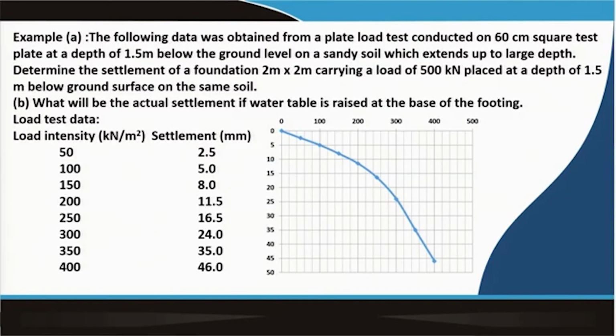by using the lab test data, because as I mentioned, field test data for clay soil we have to use with caution, because the field tests are short term tests, but the behavior of foundations on clay soil is long term. For example, the plate load test data. That plate load test is short term, but as you know, the consolidation takes a huge time for clay soil. So, those field test data like the plate load test in case of clay soil, you have to use with caution. That is why we will use the lab test data for the design of foundation on clay soil. So, first I will discuss the plate load test design, that